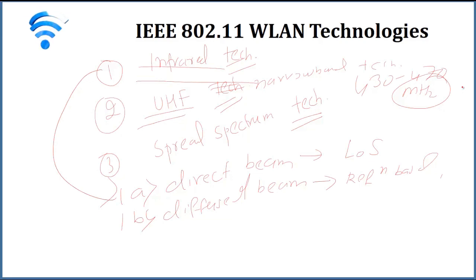So that's why these are termed narrowband. Narrowband usually describes this technology because the RF signal is sent with a narrow bandwidth, typically 12.5 kilohertz or maximum up to 25 kilohertz. The power level is again 1 or 2 watts for this data system. So the narrow bandwidth combined with high power results in a larger transmission distance.